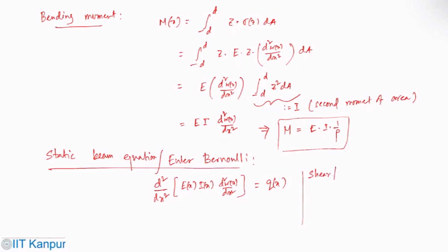Here you have shear force, which is dMx by dx, which is capital Qx. You have distributed load, that is d2 Mx by dx2, which is small qx.